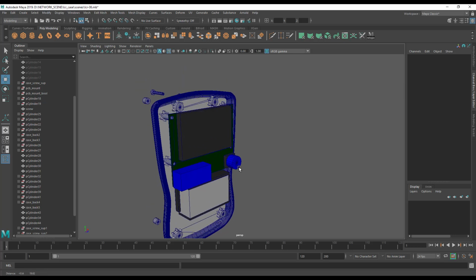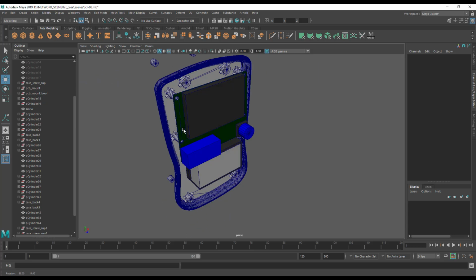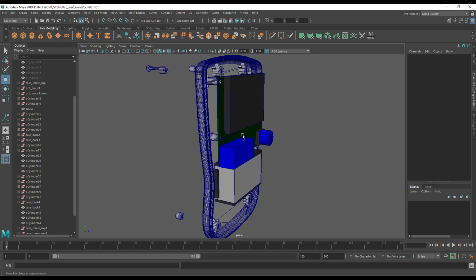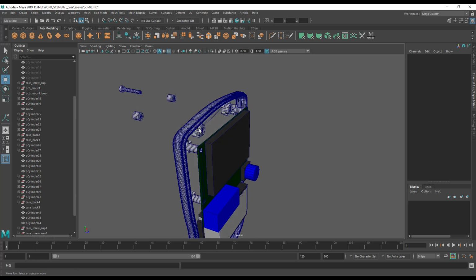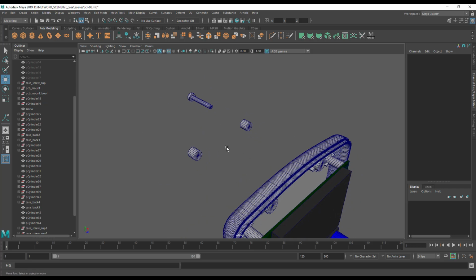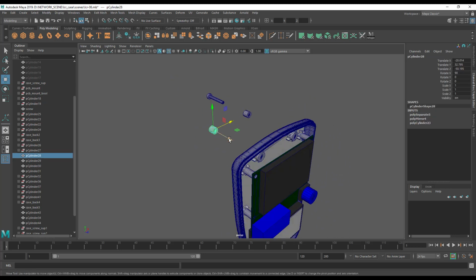Okay, so welcome back. Now we have our little holes in the back of our case and the support nubs to support the head as it goes through the case. We need to make the actual holes and the support pillar for the screw itself. So as we know, the screw thread is 3mm, so we're going to make the diameter of that 1.4 to make it 2.8. Now we're making it slightly smaller, as I've mentioned, so we can use self-tapping screws to screw